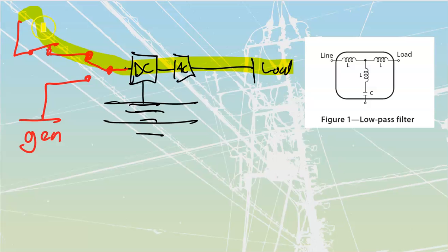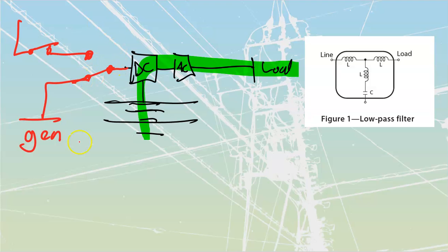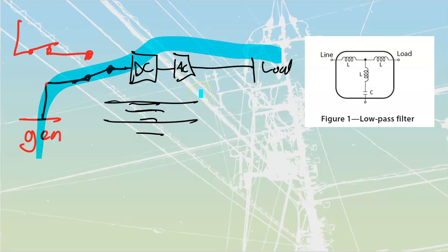If then BC Hydro fails, that disappears, then in the meantime, this thing is going to, out of its battery bank, continue to run power out to the load. And while it's running power out to the load, the transfer switch is going to switch over to the generator, which picks up, and then the generator takes over from the batteries, and the batteries go back to charging up off of the system. Provides us with complete ride through itself.